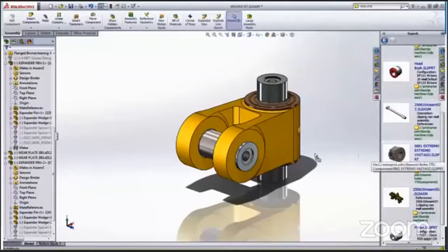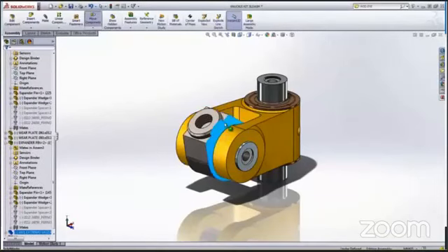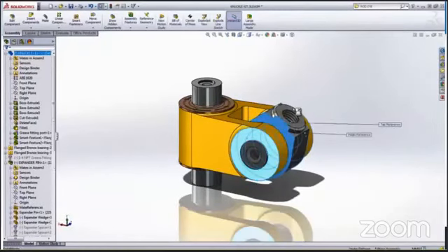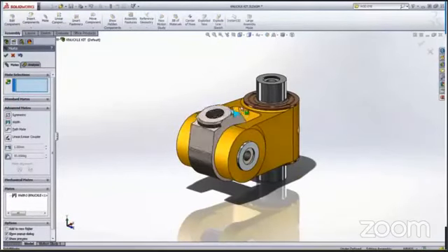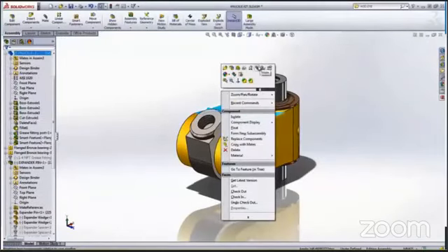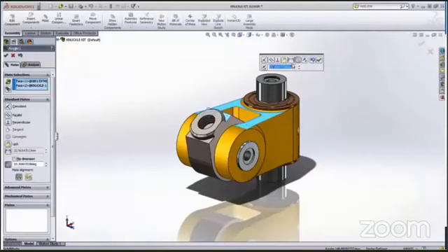We may also want to add a rod into the assembly to better define the load transfer. With a quick search, we can find this part and add it to the assembly. Let's center the rod with the width mate and then locate it at what will probably be the most extreme loading situation.